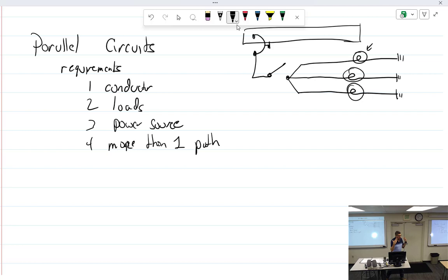So in reality, the power is coming from the battery, going to the airframe, going around the entire airframe, finding its way out that wing to that little wire, to the light bulb, and then back through to the switch and the battery, right? But that sounds stupid to say. It's so much easier to say, no, power comes from the battery up that big fat cable, goes to the master solenoid, goes to the bus bar.